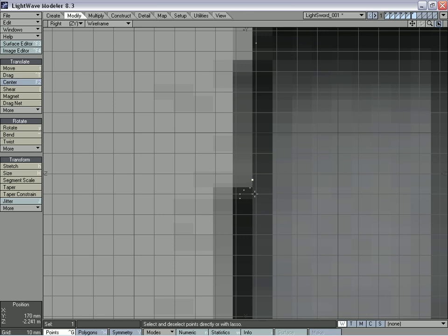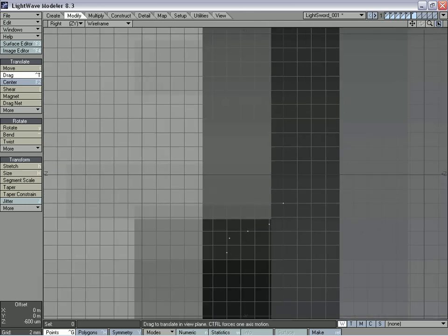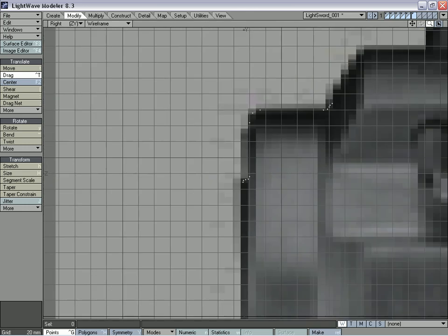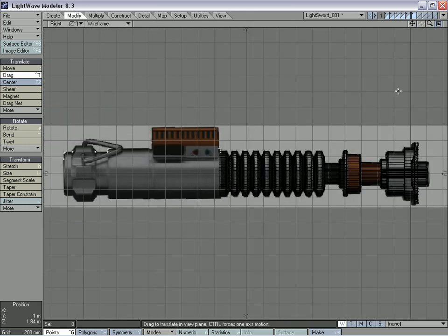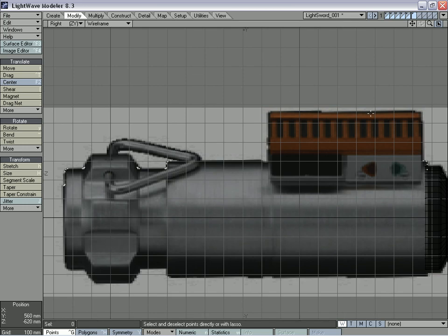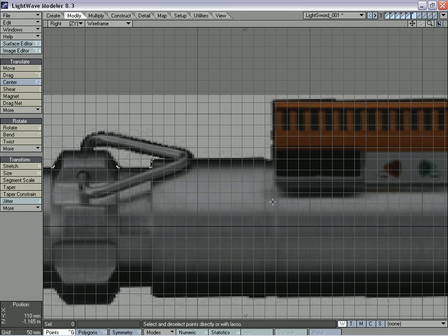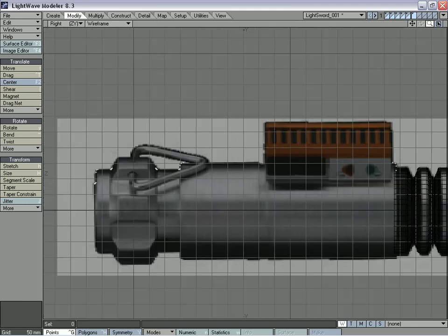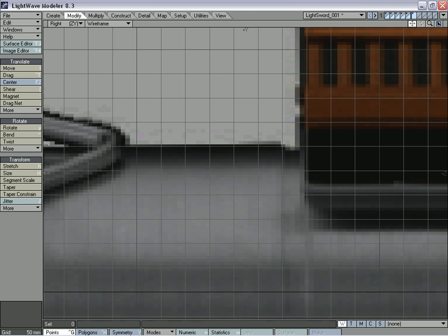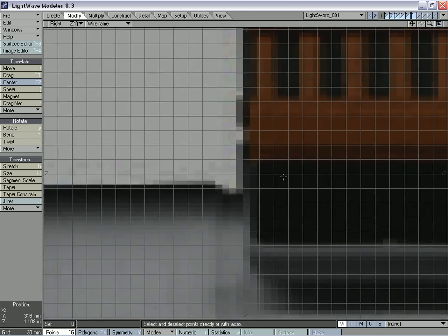Okay, and delete this point, copy and paste this one down to make it straight, which means we need to use the drag tool, Control T, to edit that just a little. And zoom in there. And there, that looks like that's good. Now, as I was saying before, we were going to use the knife tool to create this, but I kind of changed my mind, and we are going to use points to define this little inset in here.